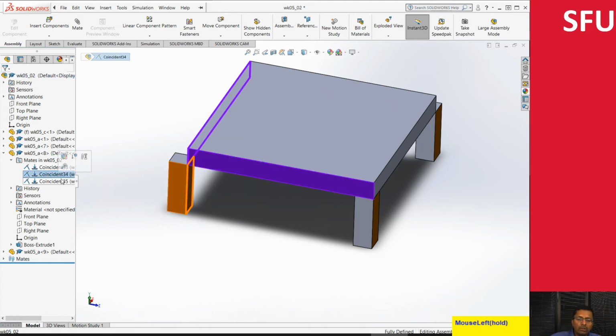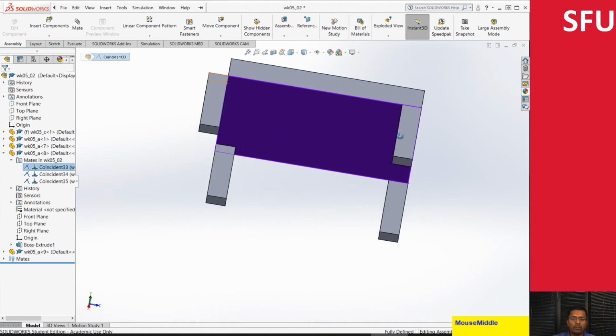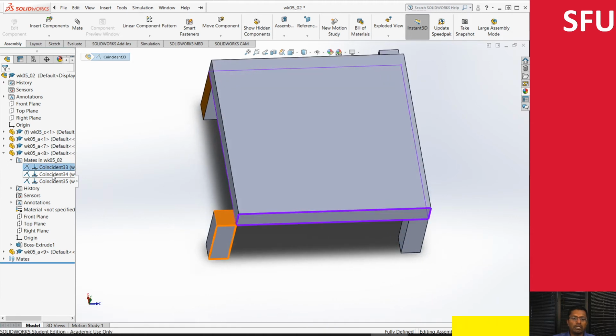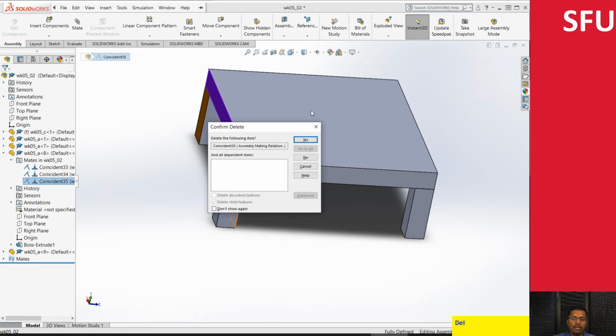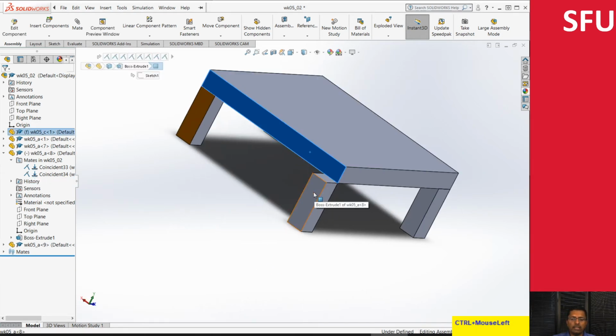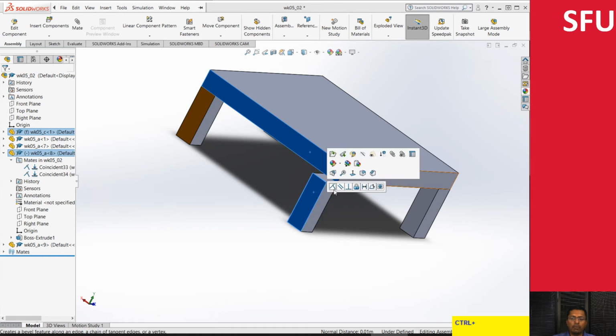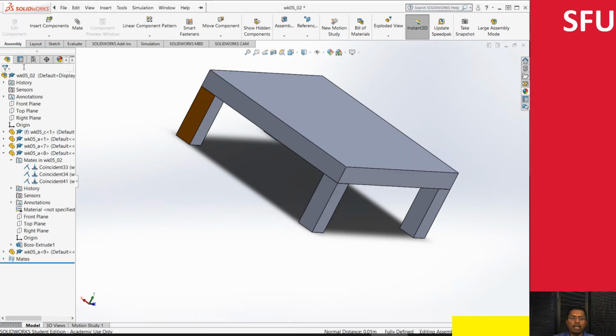So this one looks good. Maybe the top mate looks good. The second mate over here looks good. The third mate, I probably don't want that, so I'm just going to delete this one and then select this face, Control and select the other face, and then make it coincident. So now it moves my leg inside.